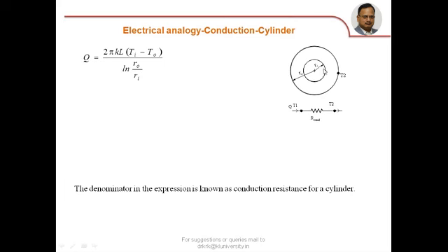For the heat to flow from inside to outside, this material offers some amount of resistance. The mode of heat transfer through the wall of this cylinder being conduction, that resistance offered for heat flow is known as conduction resistance.